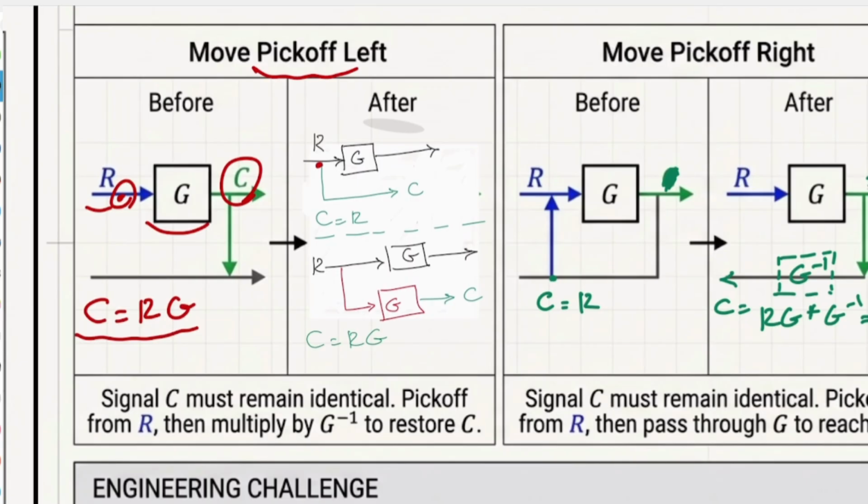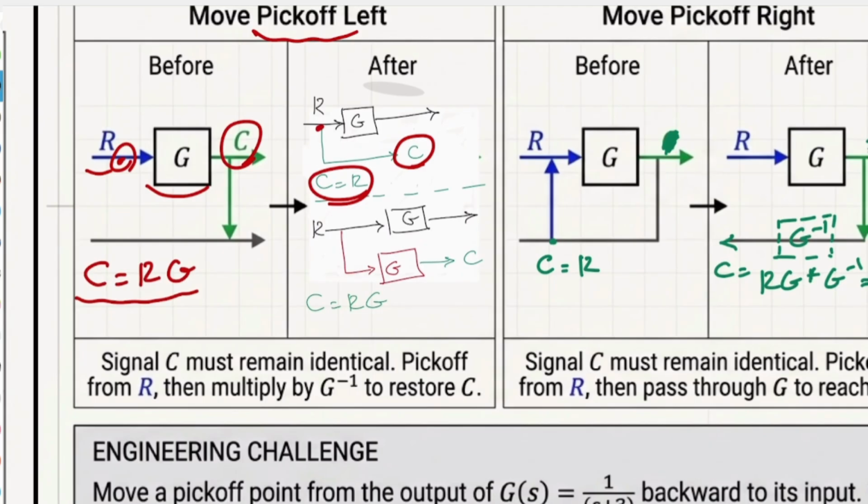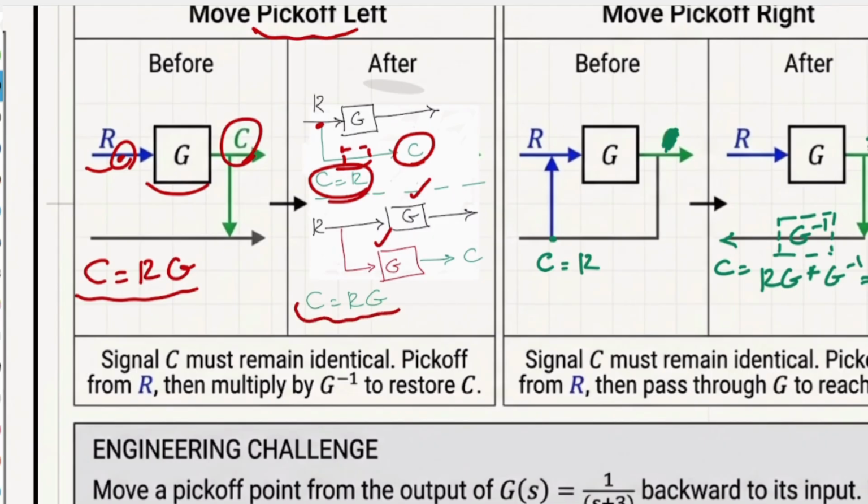So if I just consider that and don't change anything, at the end of the day my output signal is going to be just R. As you can see, there's a huge difference between R and GR, so it means that I already lost something. In order to compensate for that, we have to put another gain between my output and the new place itself. And that gain should be exactly the same as the normal gain that we used to have. So my system would be like this.